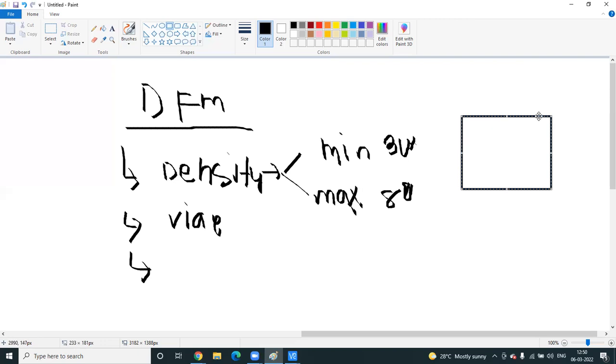But don't completely fill by only M1 100%. 100% area you will not cover by M1. That will come under maximum density. How to clean? You have to reduce this metal, delete some metal. For minimum density, you have to add some metal. You got the point? This is very easy one. But in real time, in this technology, you have density clean.